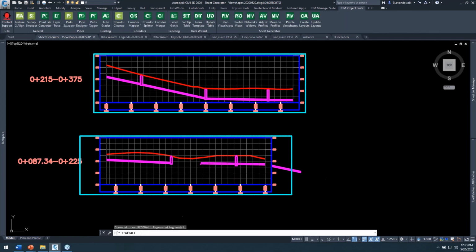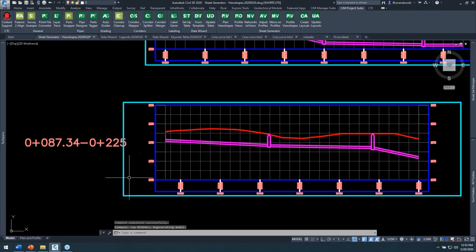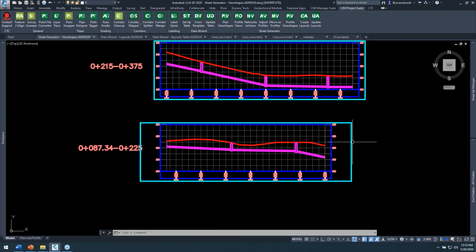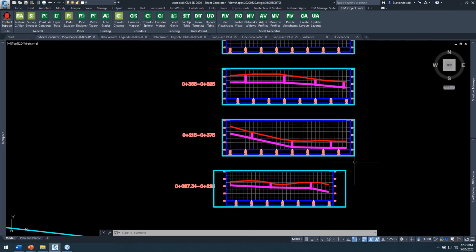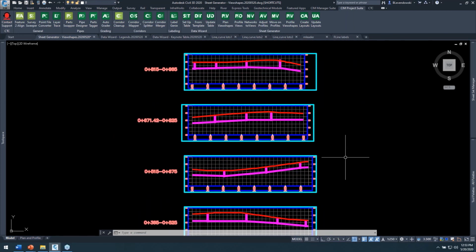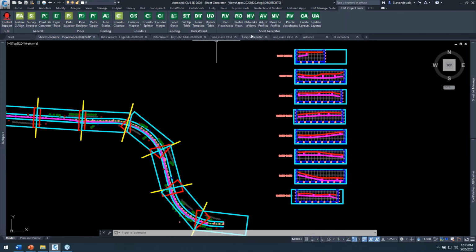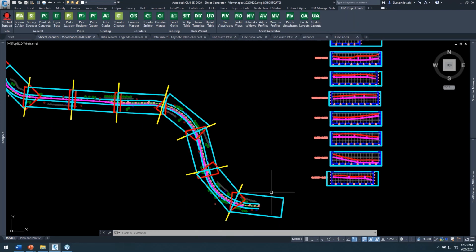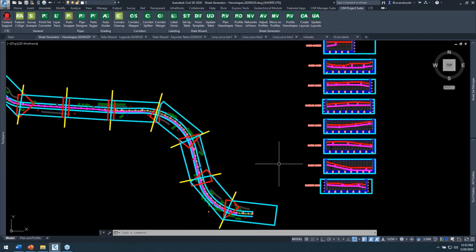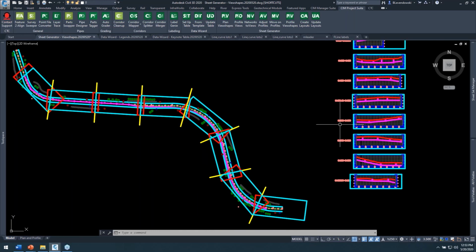Okay, refresh the view, and now it's centered. It's not right along the left edge here because of where the stationing starts. Okay, so really dynamic. You can jump between these different modules. You can massage this stuff, get it to look how you want before you actually even create the sheets. But like I said, once they're created, we can still go back and update the sheets if any of this stuff changes.